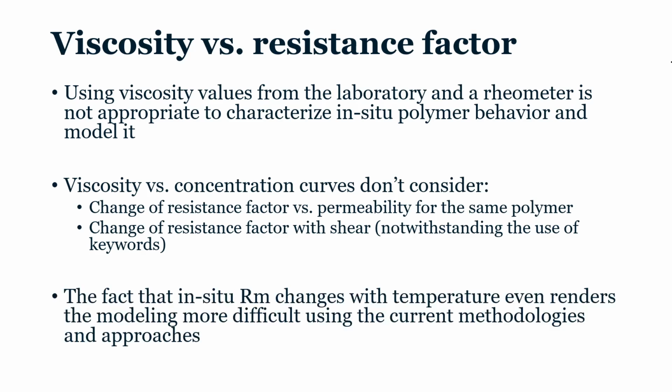For instance, the fact that the in-situ resistance factor will change with temperature makes it even more difficult. I'm just talking about some exotic polymers here, but that's the exception. That's proving my point about not using rheological curves, because some polymers will have very different behaviors in porous medium. And with one polymer or two polymers which have the same curves, you might have very different in situ behaviors.